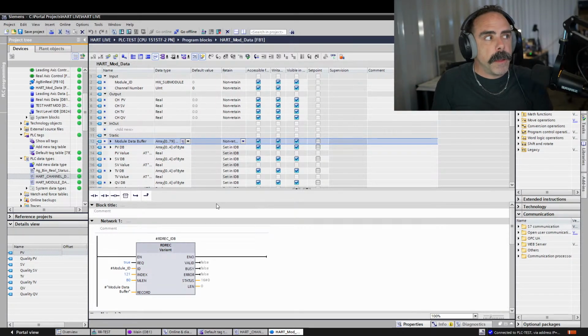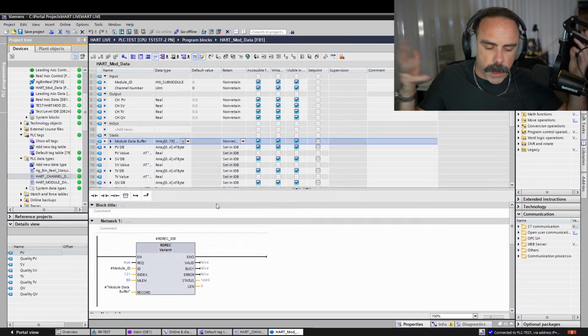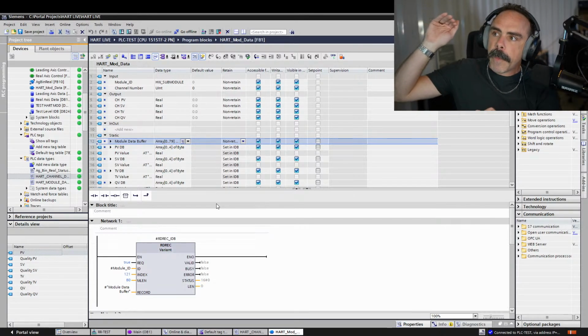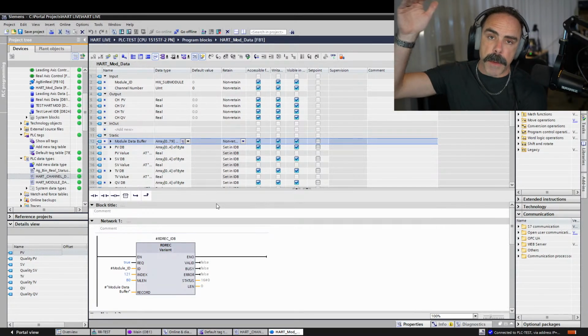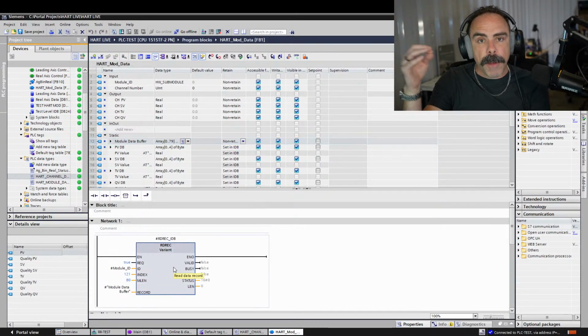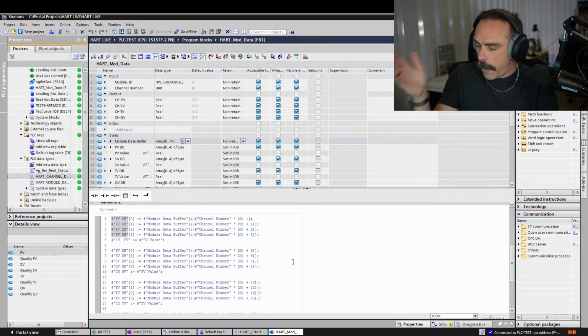And if you're kind of new to Siemens and new to programming, probably you're going to glaze over on all this stuff because this is pretty intense stuff. But I brought everything into a big 80 byte buffer. Cool. I got my data in, and that is doing this here, that read record. Now I have to parse my data. And of course, I'm swapping.